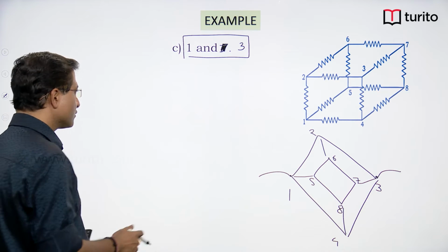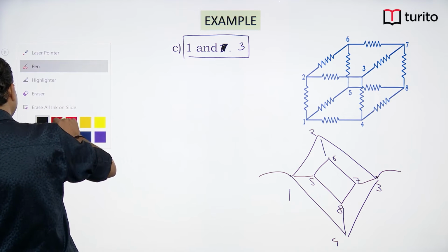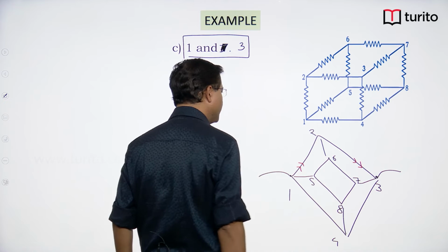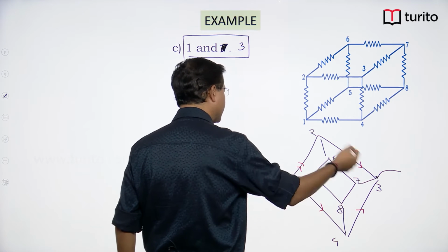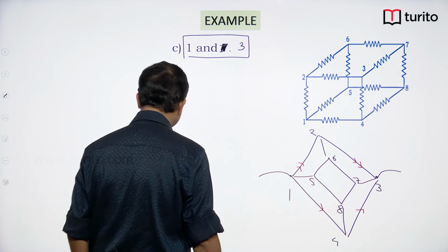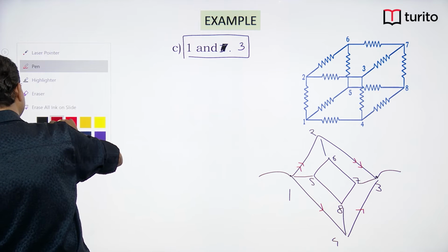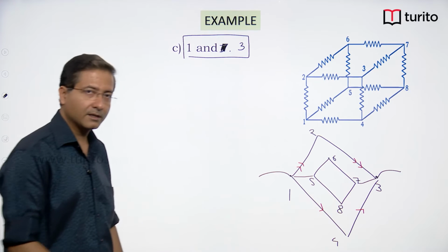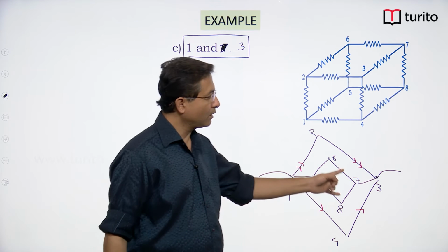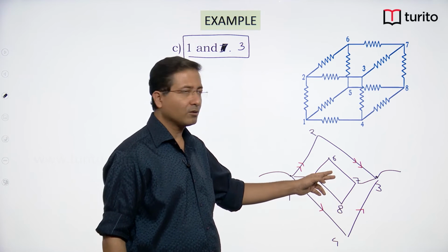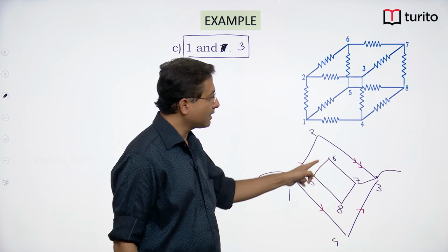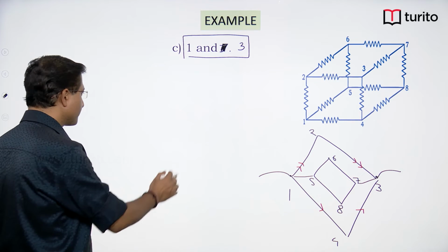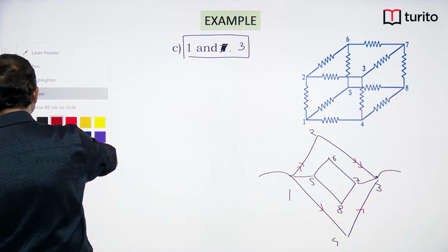Okay, so now there is input output symmetry, and only one junction involved between input and output. So this current will directly flow, this current will directly flow. These 2 resistors are of no use, I can remove. So this I can remove and this one I can remove. This is what we are getting. So 2R and 2R parallel combination will give you R. So this whole thing is R, R, R. So this inner one is of 3R.